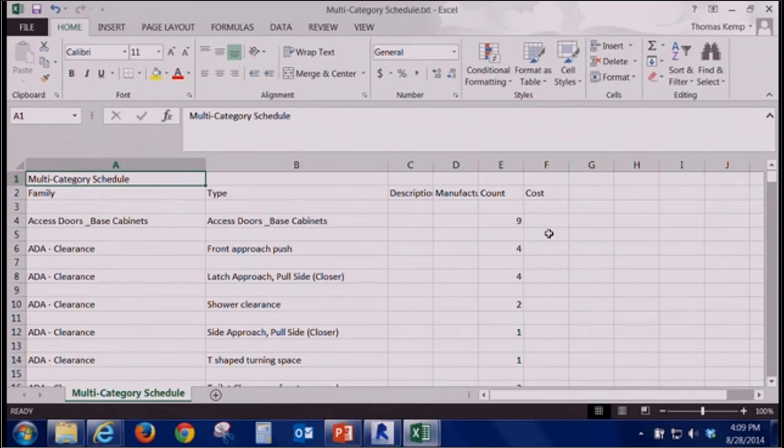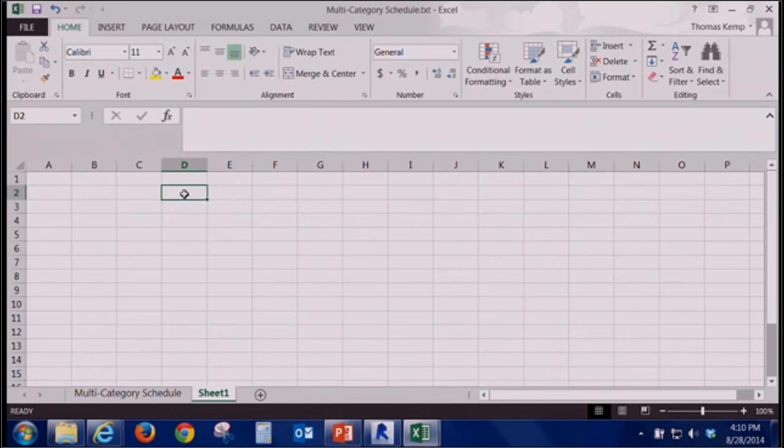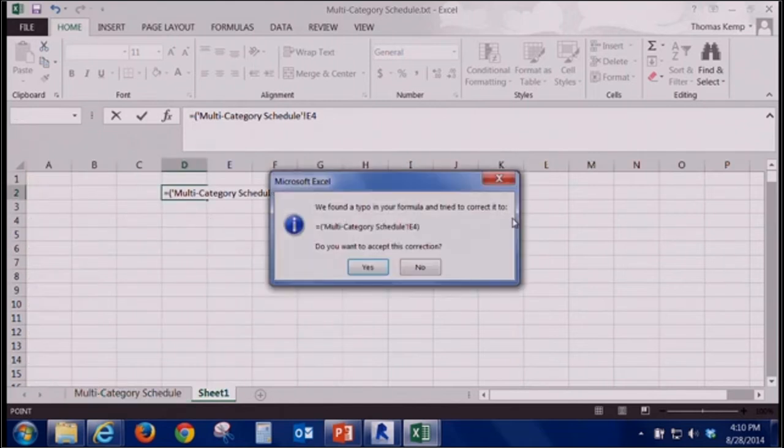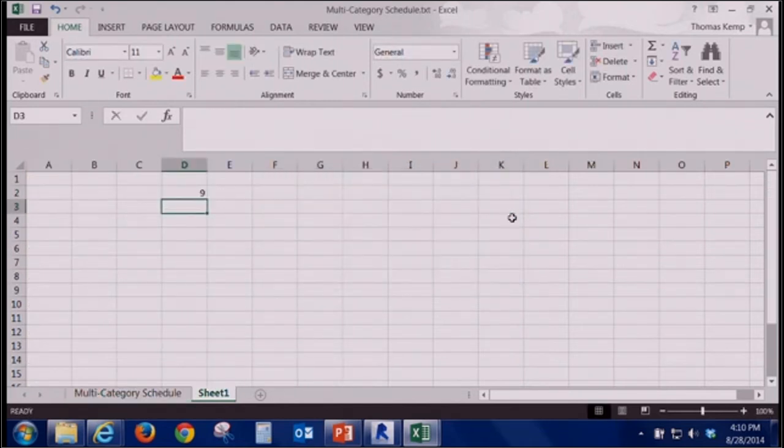So what I've done in the past, if I want to do some other calculations or analysis on this, is just have one tab here that is my information that I get directly out of Revit, and then set another tab up here, and just set any calculations up here that refer back to this tab. So if my information coming out of Revit changes, I just drop it back in that initial tab again, copy paste it in that tab, and everything updates.